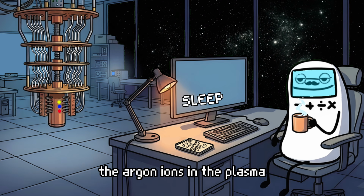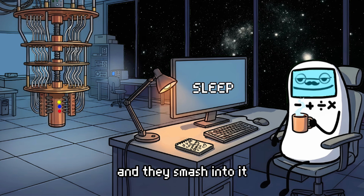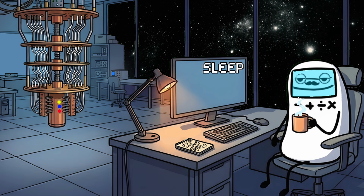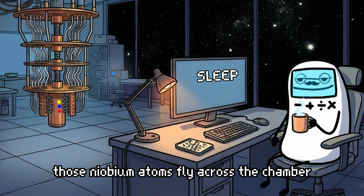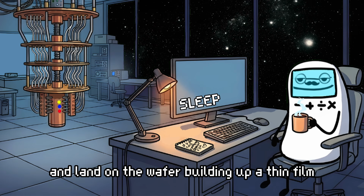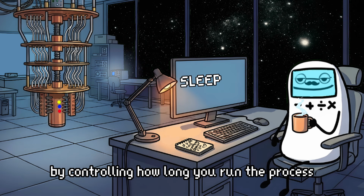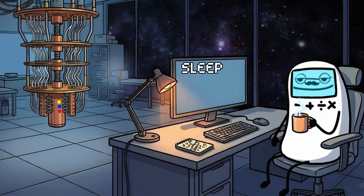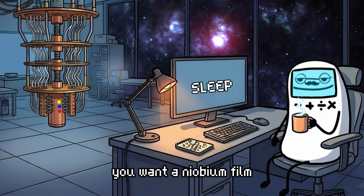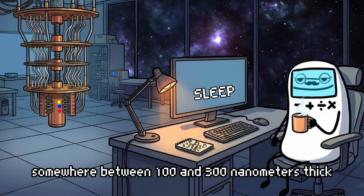The argon ions in the plasma get accelerated toward the niobium target, and they smash into it, knocking out niobium atoms in the process. Those niobium atoms fly across the chamber and land on the wafer, building up a thin film. You control the thickness of the film by controlling how long you run the process. For most qubit applications, you want a niobium film somewhere between 100 and 300 nanometers thick.